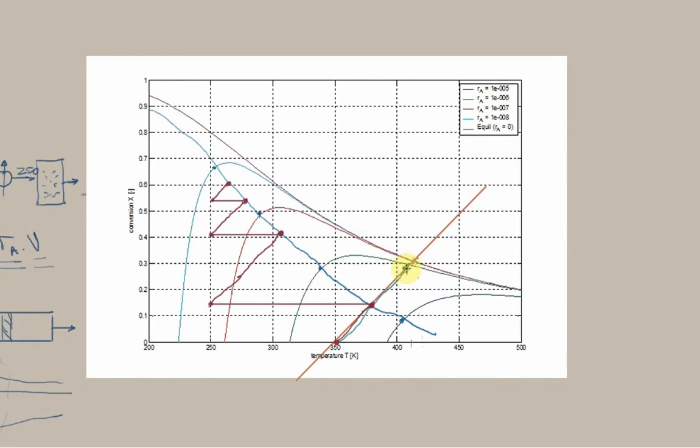So we accept this. If we change the optimality criterion, so instead of trying to achieve small reactors, we say, okay, if we want to reduce the number of reactors, then we need to accomplish a greater conversion. So we can't be optimal in terms of reaction rate anymore, but let's push conversion as far as we can without running into serious volume problems. So let's take it there.